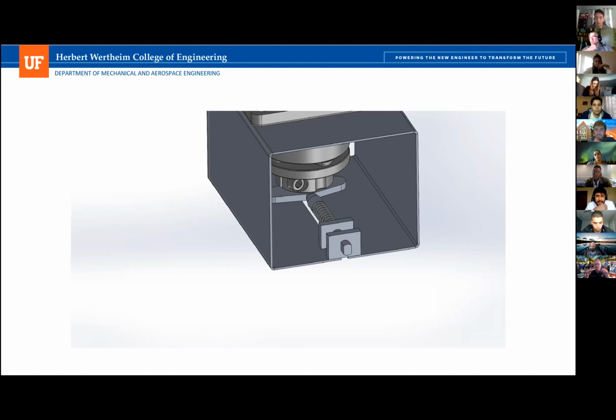My guess is, the way this is set up now, as soon as you turn that motor on, it would just shred that spring thing. It would just blend it. It doesn't look like it would be as forgiving as it shows in the video. But the thought was there. It looks good, but like Andy said, maybe a little bit more thought into that cam shape. Increase that width, decrease that length a little bit. Closer to a circular pear shape.